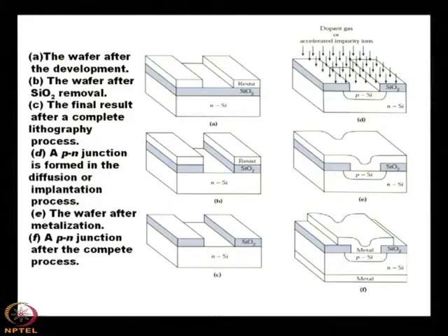Yes. Here, that means when we wind up doping with the P junction, is it pushing the N dopant? No, it is not pushing, because you know that the mechanism of doping is that it is taken inside the crystal lattice. So, there is no pushing or pulling in case of semiconductor doping. They are forming the bond, and where they go, we have discussed this earlier also: vacancy. So, if there is vacancy, there will be diffusion. If there is no vacancy, there will be no diffusion.